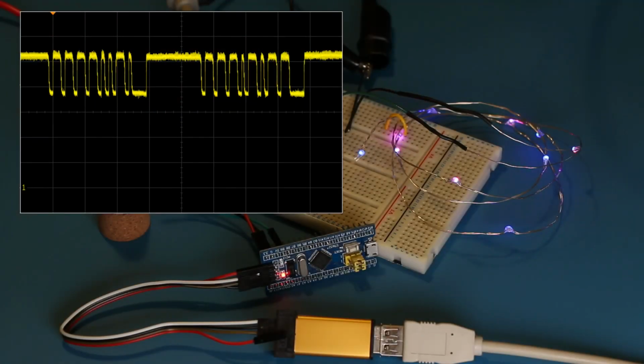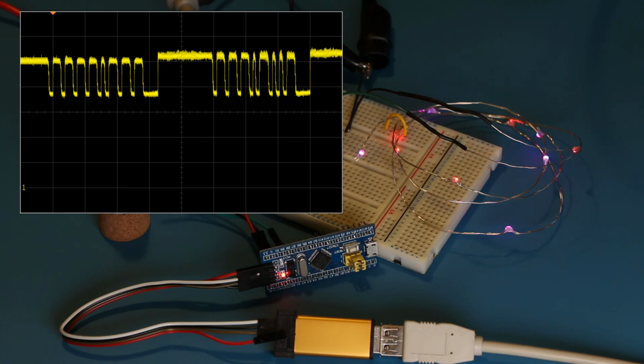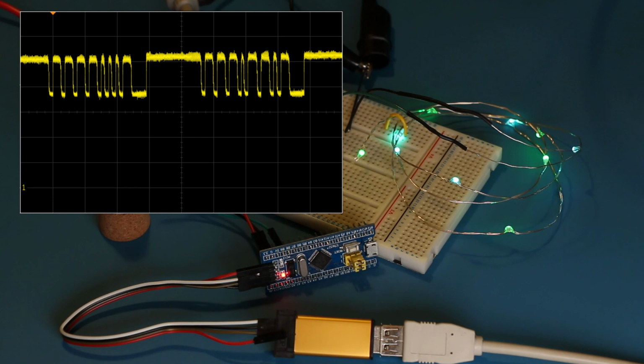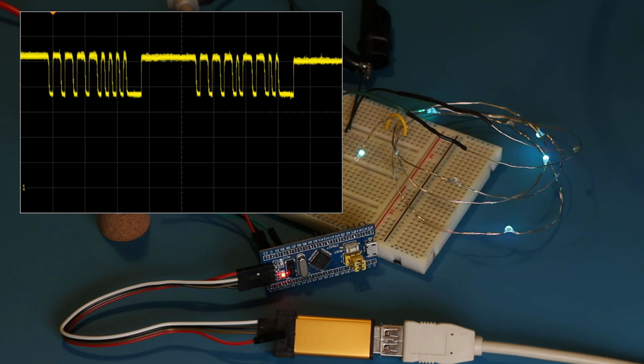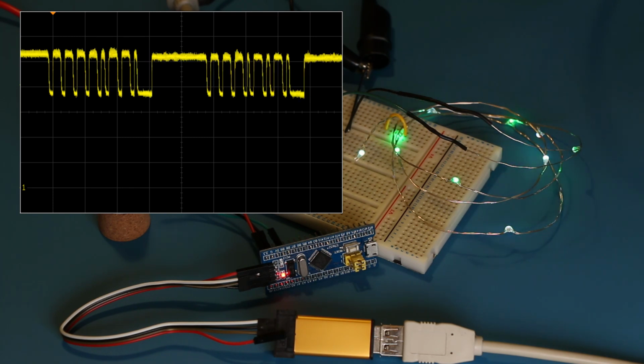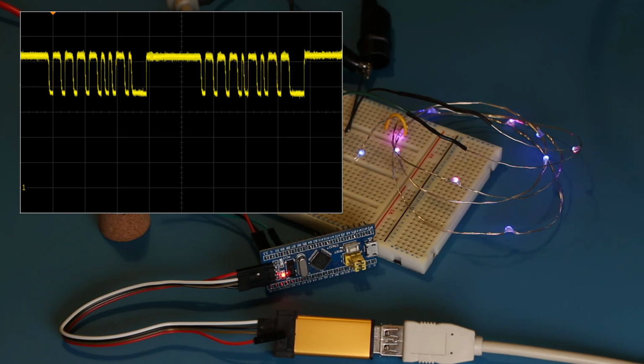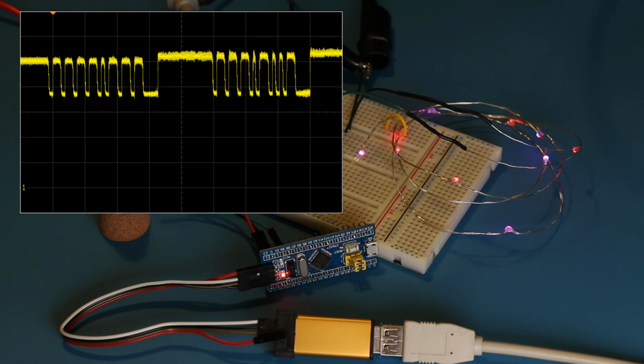In the next video I'll look at using something more suitable like a timer with DMA or perhaps SPI to make these waveforms. The current bitbang implementation is very restricting in terms of what we can do. Any processing that might be required during the packets will immediately push the timing out of spec, and this current implementation is not very flexible in terms of what colour we want to use.